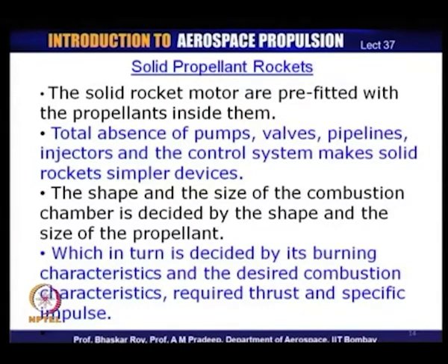Now, this means that the shape and the size is decided by the burning characteristics of the propellants. The propellants are the fuel and the oxidizer. In case of solids, there is a mixture of fuel and oxidizer, and the desired combustion characteristics, the required thrust, specific impulse, the fundamental parameters are decided by the burning characteristics of the propellant.